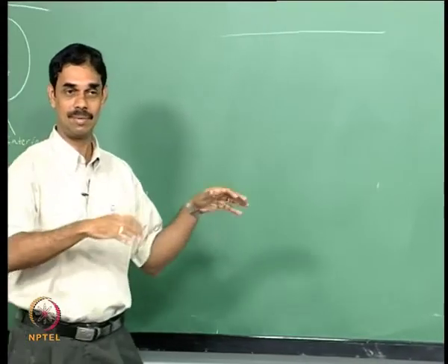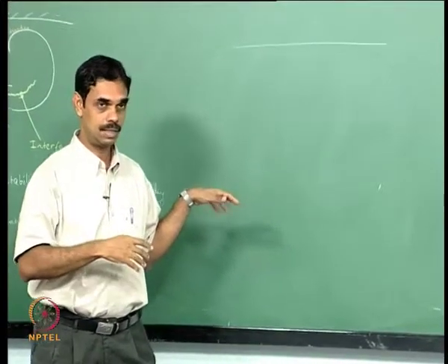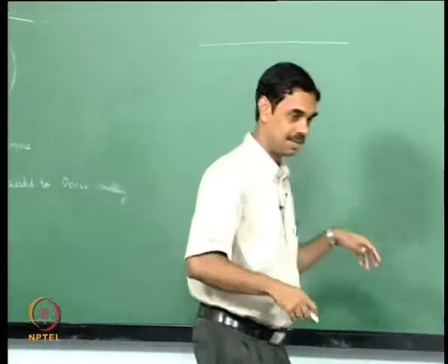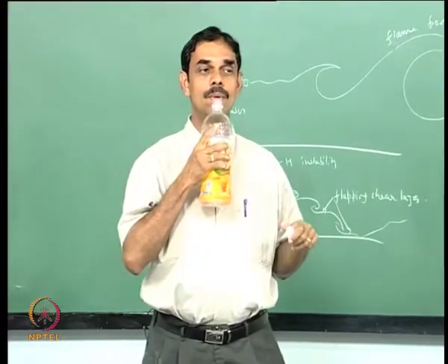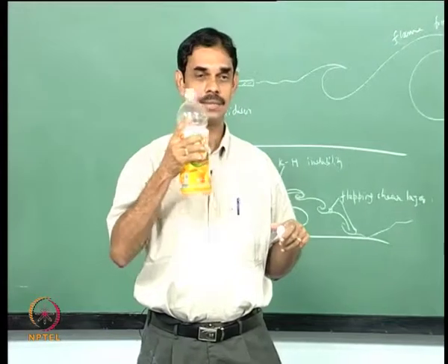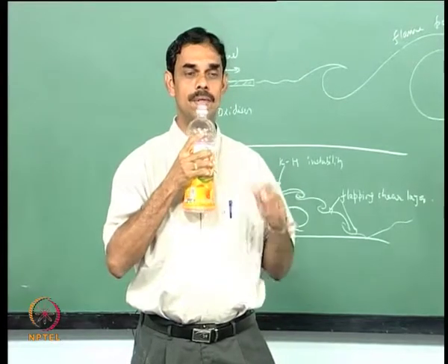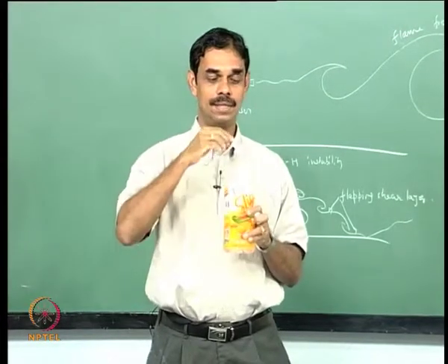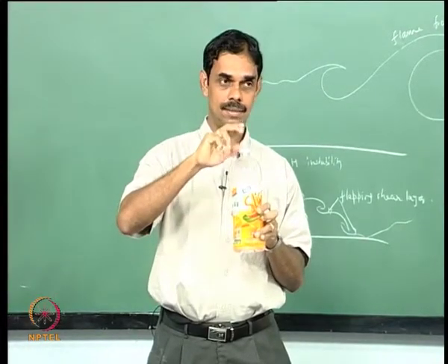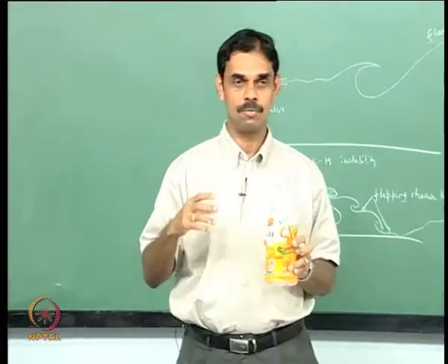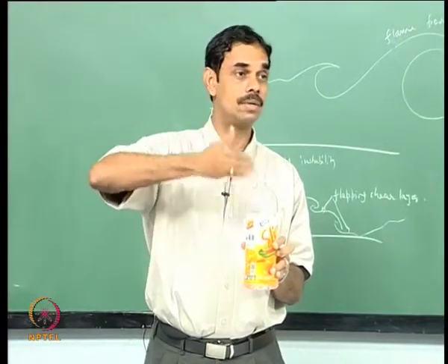So your answer will have to wait a little bit while I speak about aerodynamic generation of sound, and I don't know if the water height in this bottle is right to generate the sound, but let's try. Here there was no combustion. I'm blowing, and I'm actually shedding vortices here, and there is a resonator attached. Aerodynamic sound is produced by vortices when the vortex has a trajectory which is perpendicular to the acoustic streamlines.